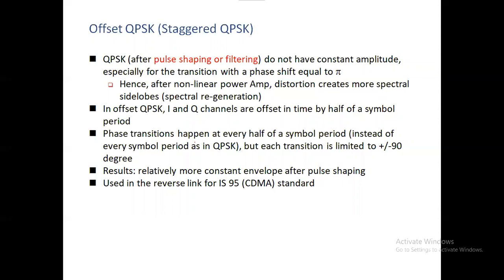And this has a relatively more constant envelope after pulse shaping. So this scheme is used in the CDMA standard IS-95 for the reverse link.